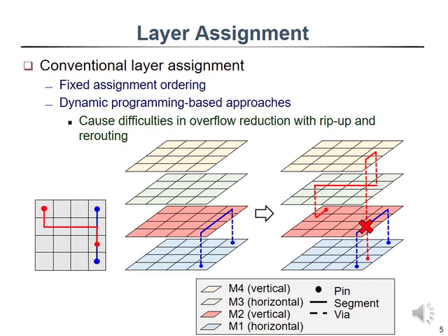Here is a simple example. In Figure 1, it presents a feasible two-dimensional routing pattern. If the routing order is blue net before red net, the red net will be blocked, because the blue net chooses the shortest path, which is the optimal solution at the moment. No matter how the red net is assigned, its optimal solution will end up with at least one overflow.